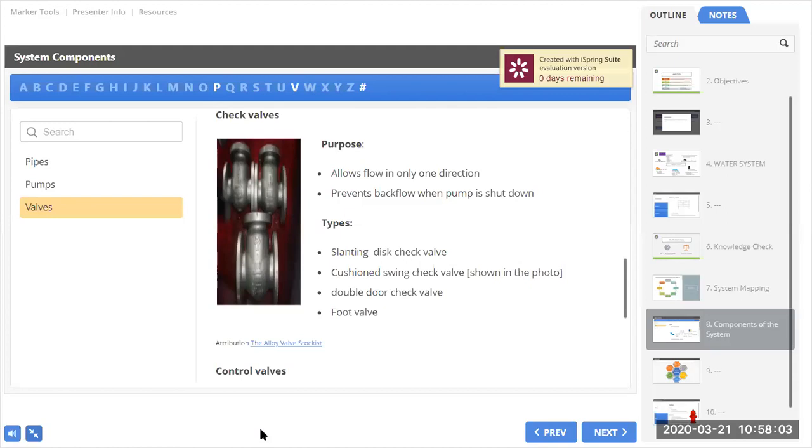The end of the hose was dropped into the tank of chemicals. And then you had back siphonage, you had water basically flowing back into the hose. And that water ended up in the distribution system. Because at the same time they were doing that, some repairs were going on in the system that allowed the pressure in the system to drop. So you had back siphonage and the chemical went into the system and many persons were affected. So we have to be very careful with these kinds of things.